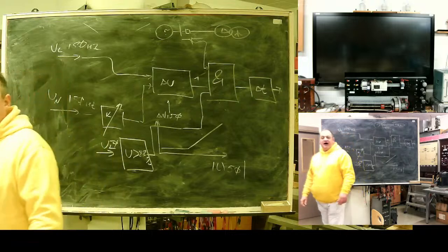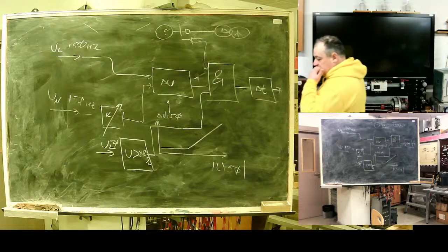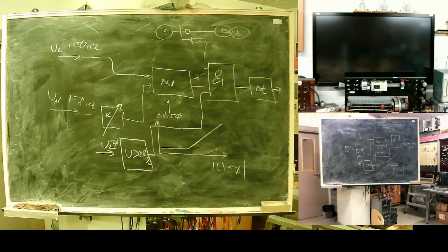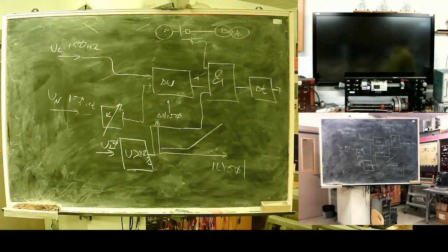Because under-excited, even if there is no exciting current, the generator will produce some voltage. There will be something, some noise. And this can be treated as a difference in third harmonic voltages, as a disbalance. So to prevent this, a safeguard should be placed.